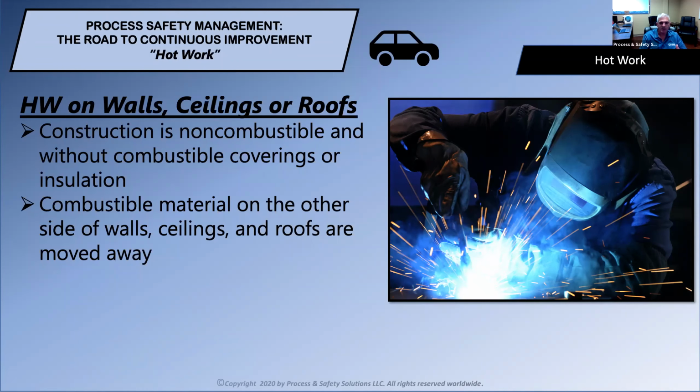So they did all of the right things from the roof standpoint, but they didn't realize that on the other side of the roof was an open field. Well, they may have realized it, but didn't have a fire watch in that area or that could see that area. And what occurred is, as they were grinding, sparks flew off the roof down onto the dry grass on the other side of the roof, started a fire that eventually, because it was surrounded by an open field, also resulted in significant loss of materials,